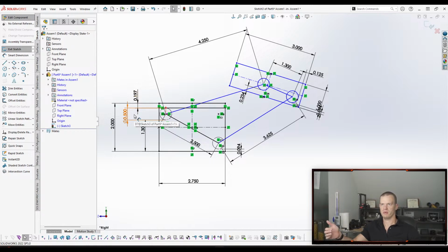Now that I've rambled for a couple of seconds and had some time to think. One, look at top-down methodologies, specifically skeleton sketching. We have a video on that. There's also a really good PDF out there on the interweb somewhere that somebody did up. And number two is try to reduce the number of dimensions you have in any one sketch as much as possible. I think those are probably the two biggest things.